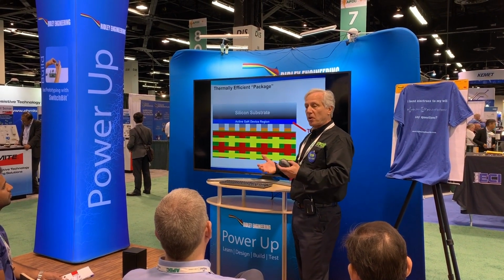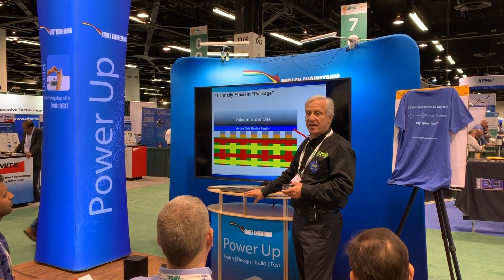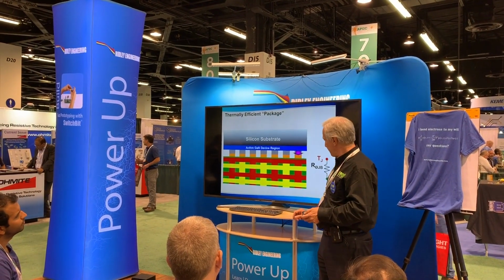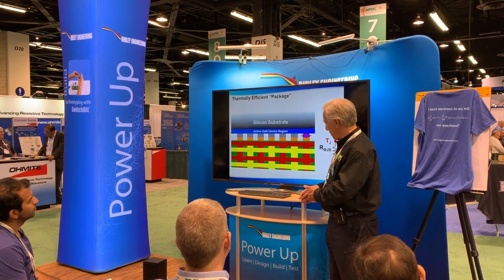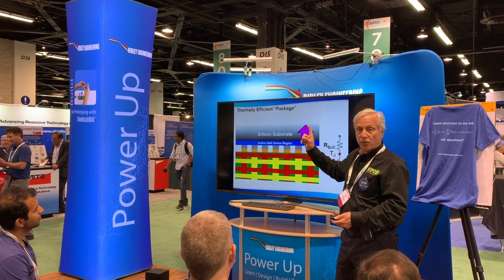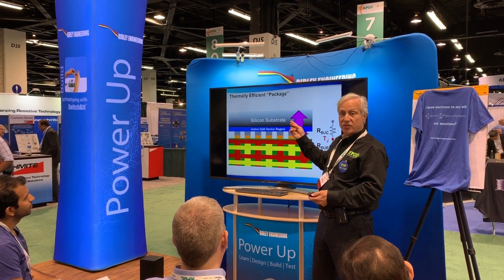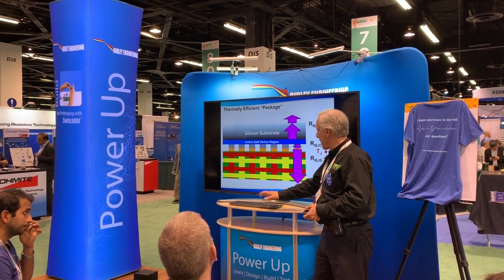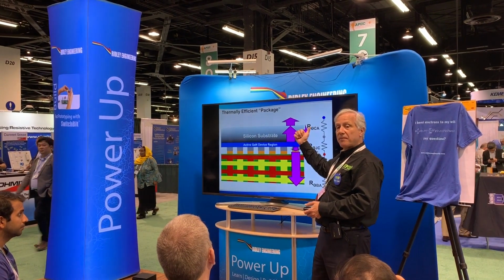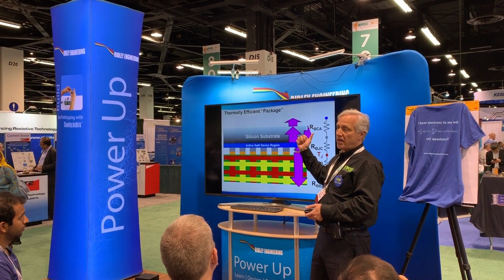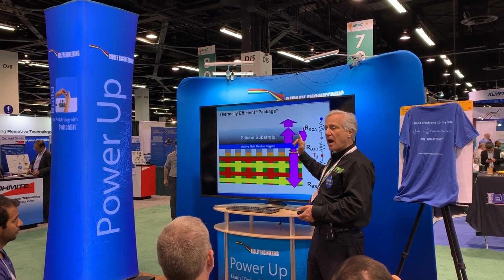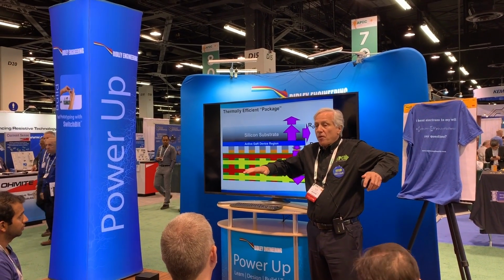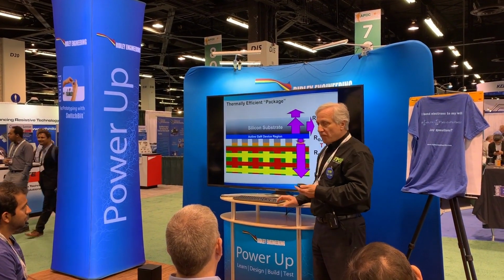When you're worried about the thermal management of your device, you've got to look at all the ways that heat gets out, and you do that in terms of thermal resistances. One is down into the PC board. We call that theta JB. Up to the back surface, theta JC. You look at a bunch of silicon parts that give you theta JCs all day long. And then you've got to the ambient from your board, and to the ambient from the case. But you also have, in the case of a packageless device, sidewall radiation. The sidewalls on all but our largest devices are actually more area than the top surface. So it more than doubles, like origami, it folds out, and it's more than double the effective area of the device as a result. So you get a thermal advantage, and we can quantify that.